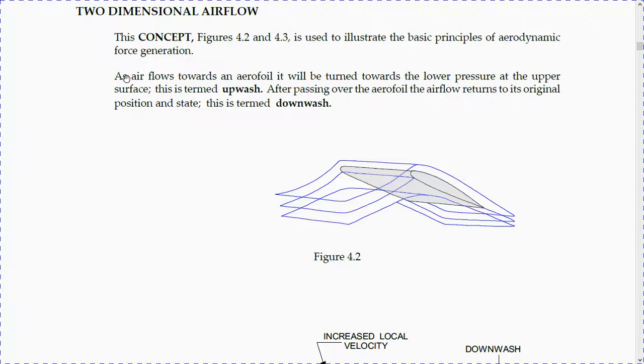This is the upwash, so it will be sucked in even before it meets the airfoil, as we can see here. So air starts to bend and move to the area of low pressure even before meeting the leading edge, and of course it will then spread up and down. It will create the wing flow, but even before that there's the upwash.